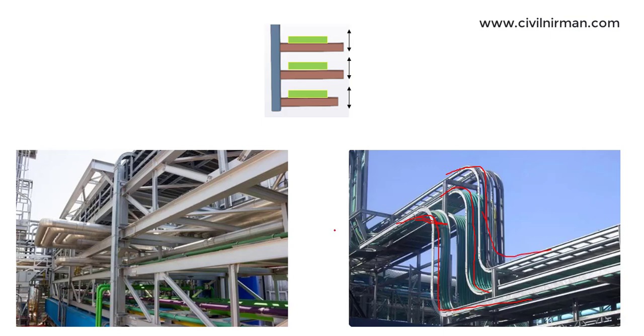So all this information you will get in your 3D modeling. You need to review that based on this particular segment. It will be a condition something like this, right? So you need to identify this clearance, center to center distance between the tray elements, whatever space they require in order to put the cables over here, or in order to operate for the installation part, or whatever the cantilever support requirement they have. All this information you need to discuss with the particular disciplines in order to work out and start providing the loading information or to freeze your structural geometry.